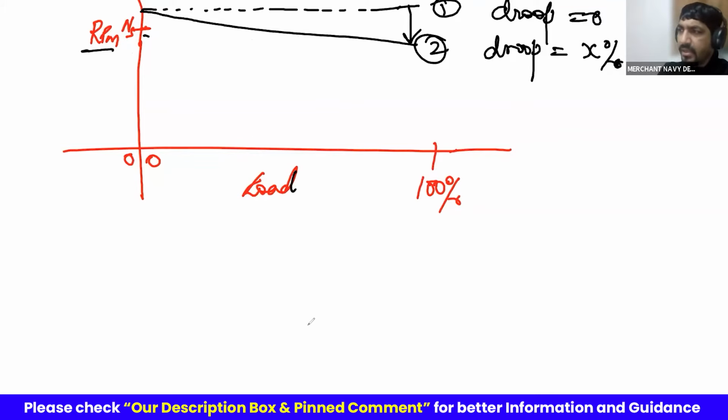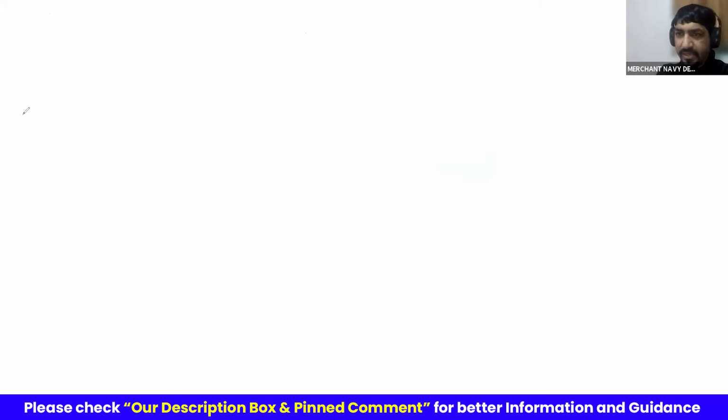Now, why is this important? Well, when you run two generators, if you do not have the droop, you can't balance them. For two generators to come in parallel and be stable while running, the droop is important, because they can share the load. If the droop is not there, they cannot share the load. So here we're talking about the frequency. Sir, why is droop needed for sharing loads? So that's another question. Okay, then you can understand this way.